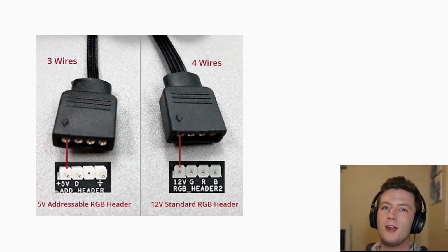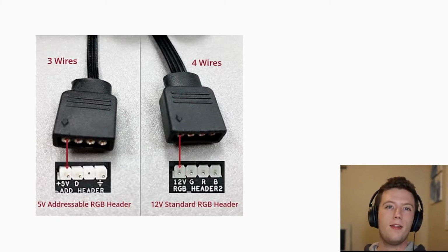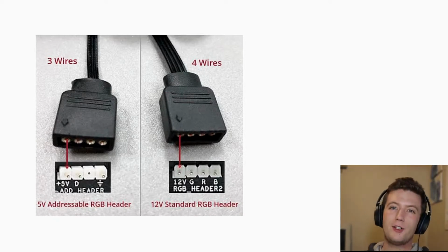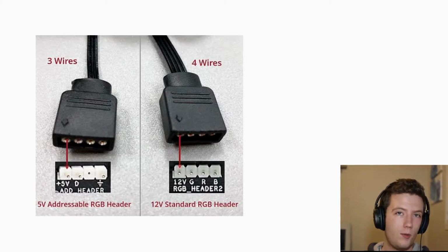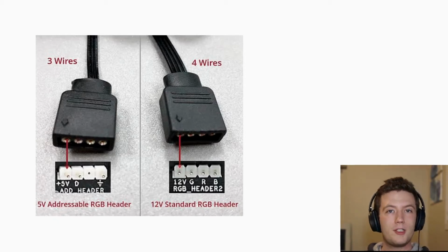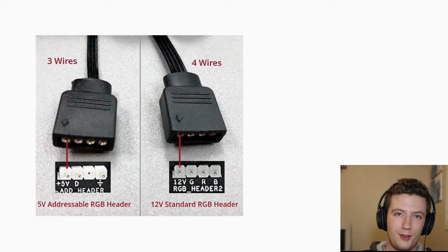Make sure you download the app that is actually supported with your motherboard for controlling your motherboard headers, if applicable, if you're using that method, as well as make sure that every light that you buy, if you're buying more than one, they're all supported and certified by the program that you are using. Just to be careful, they should all work as long as you did find the correct header and you're buying the correct set of lights, 3 wire or 4 wire. But just to be careful, make sure that they're certified for, say, AuraSync if you're doing an AuraSync build, or for Razer Chroma if you're using Razer Chroma.